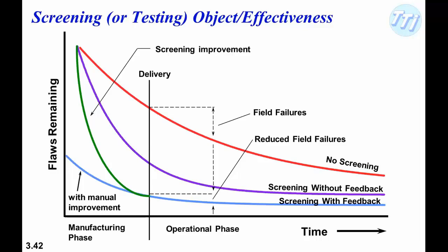We all looked at each other and said, I wonder what that was. Well, we didn't have to wait for very long, because 10 minutes later something else went bang, and not too long after that it started sounding like popcorn. What was happening was that all of the electrolytic capacitors used for noise bypass in the signal conditioners were blowing due to old age, or the old age wasn't very old, but the fact of the matter is that there were a whole bunch of faulty capacitors in the system.